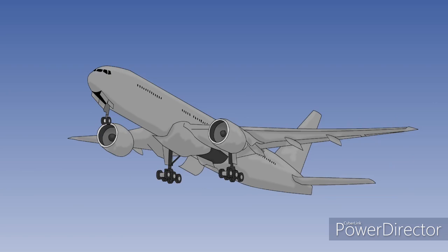Considering all the foregoing factors, we can conclude that at a given altitude, airspeed and power setting, excess thrust depends on the amount of drag being generated, and this in turn will depend on configuration, weight, and whether turns are required. The control surface deflections required to balance asymmetric thrust will also cause drag. It is essential, therefore, that after an engine failure, particularly during takeoff or go-around, drag is reduced and no turns are made until safely clear of the ground.